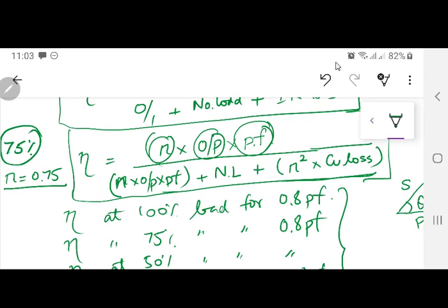Okay. Any questions with this? So whenever your transformer is complete, and I hope on Monday when we rejoin, everyone has calculated your percentage Z, done your previous work, and your percentage Z is fixed at 4.5. The value which we calculated in the last lecture was 4.72. So you have to reduce it down to 4.5, and I have told you how you are going to do it. You are going to redesign your low voltage winding so that it has a small radial build, so that you will then have a little smaller B1.